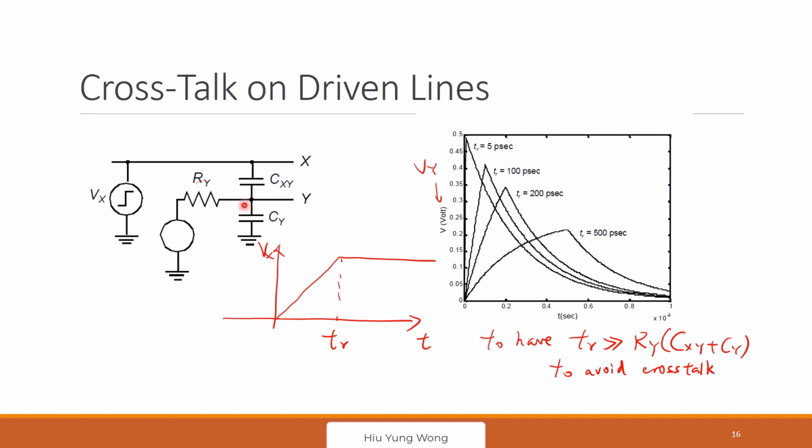One is that you either tie this node stronger to the VDD or ground, then I cannot change it. Or this signal goes slowly. But this is all against what we have nowadays. The signal is so fast, the coupling capacitance is so large, so we will have a lot of crosstalk that you need to pay attention to. Okay, any questions?